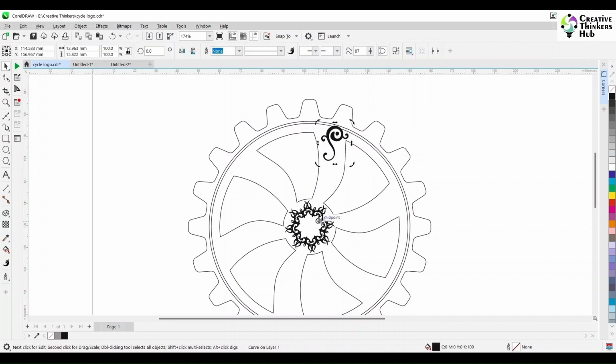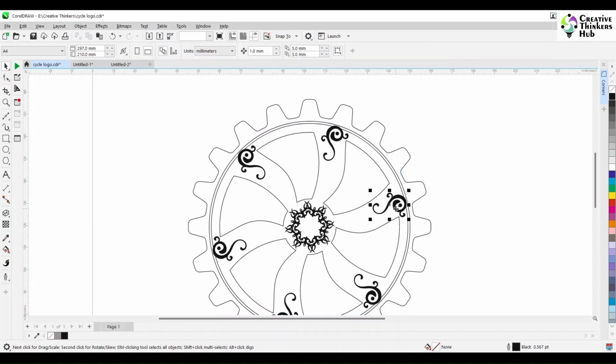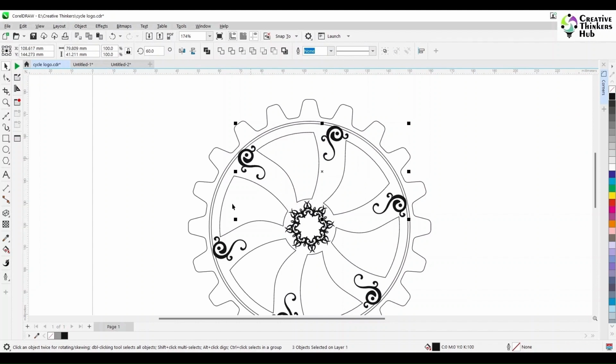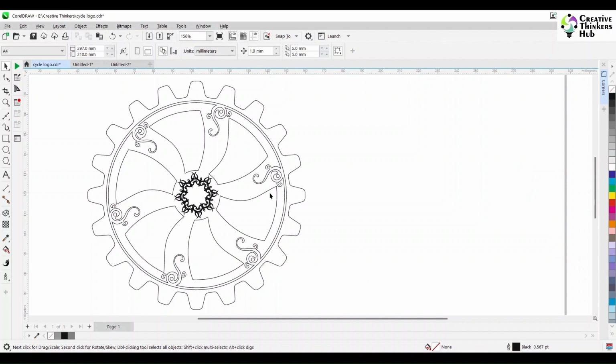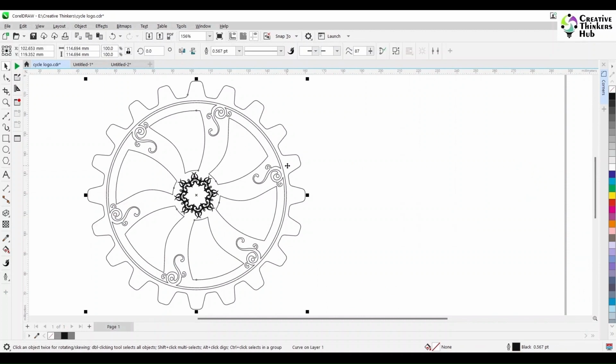Now you take the center and put it at the center of the gear, and then right click, left click, and Control D. So you get it all round. Now select all of them and select the trimmed circle. Okay, and weld all of them. So this is what you get. Delete the unnecessary parts that we don't want.